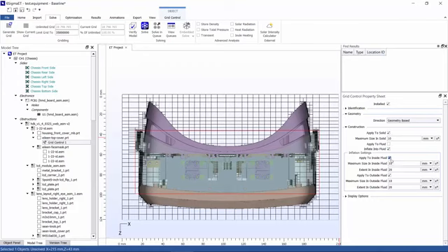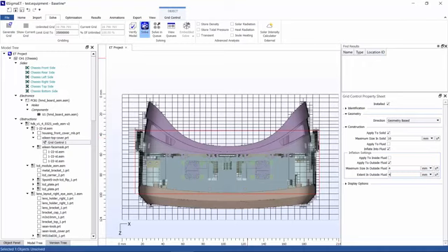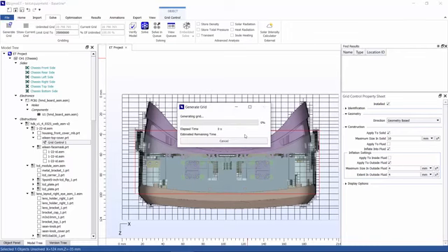And in this case, I just want to check the outside fluid, and I'm going to give it say a maximum size of 4 millimeters, and then I'm going to extend that maximum size of each grid cell, 4 millimeters, into the surrounding fluid. Now I'll just go ahead and generate the grid to show you the difference that this will make.